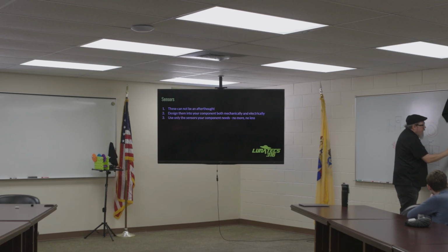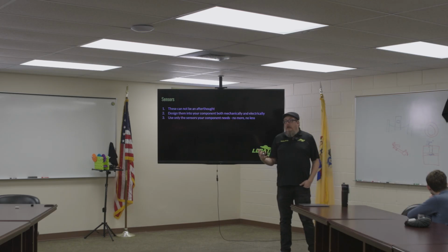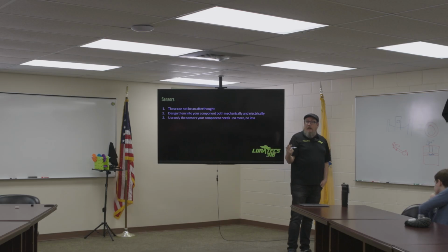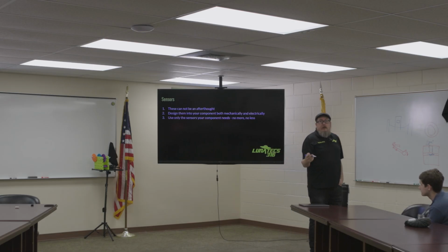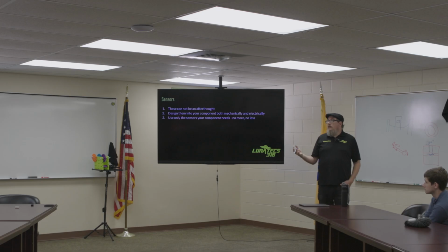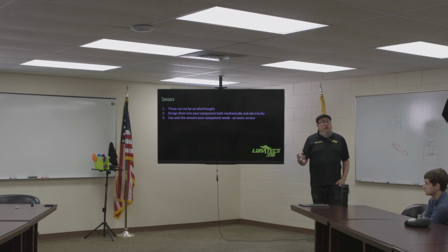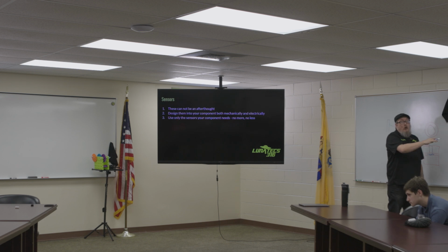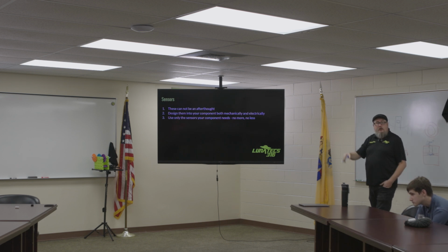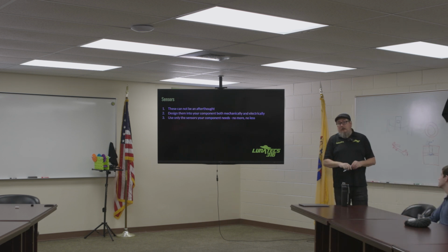So you need to run 5 sets of electrical, which come in 2 pair, right? A red and a black. You have to run 5 sets of CAN. Well, you could probably get away with 2 sets of CAN and daisy chaining them up there. But that's a lot of wire. And that wire then has to extend and retract. It's not easy to do.